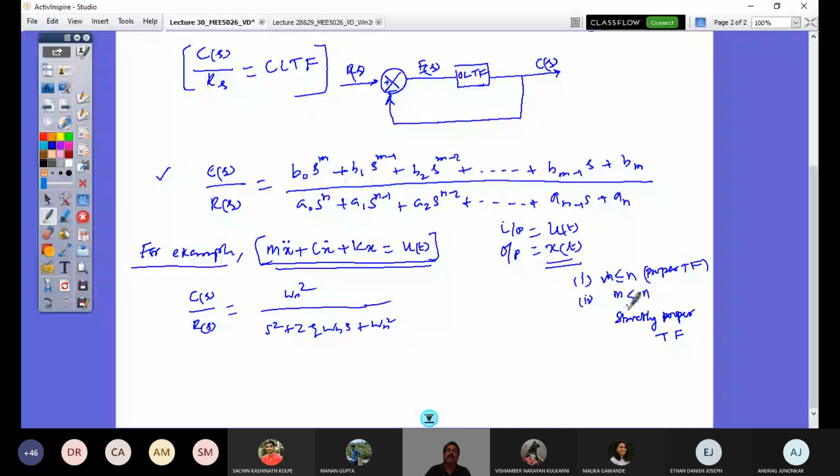So you would see that the numerator polynomial order is always smaller than that of the denominator polynomial. And the denominator polynomial is very, very important. That denominator polynomial is actually the determinant of SI minus A that we have looked at. That polynomial is what is there in the denominator. You have to connect all of them. So if I have my A, what is A here? It is the state matrix.